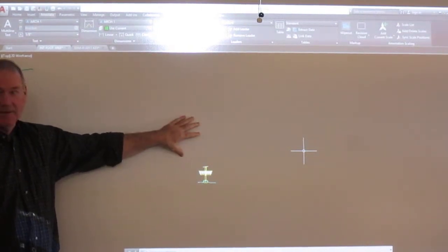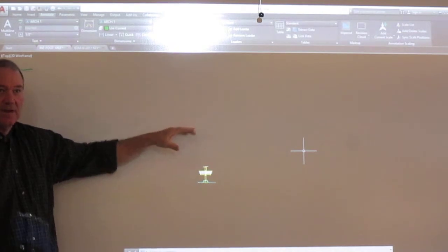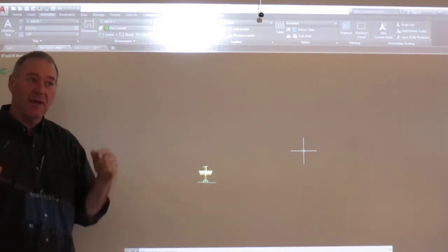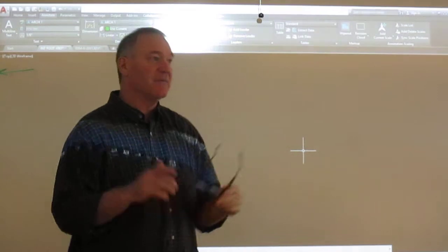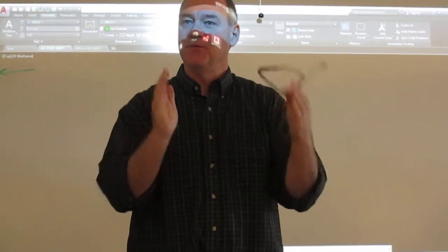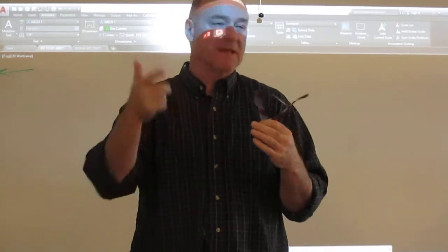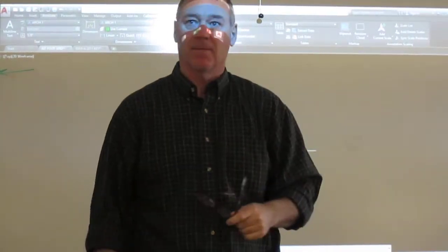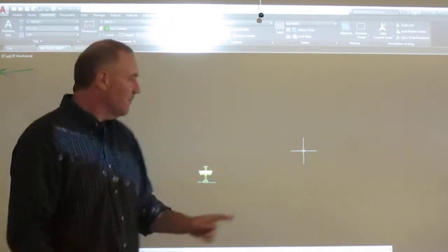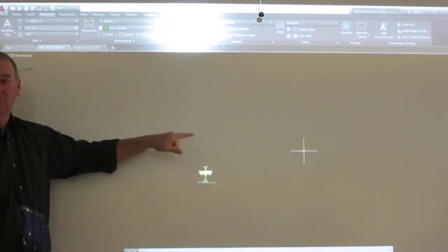We're going to print it at a different scale. Remember, we're comparing and contrasting the two ways to do XREFs. One has a set scale, fully annotated, everything's done, but you do not have the option of changing the scale with it. You always got to print it at that scale. The way we're doing this one is we're not annotating, it's 1:1.